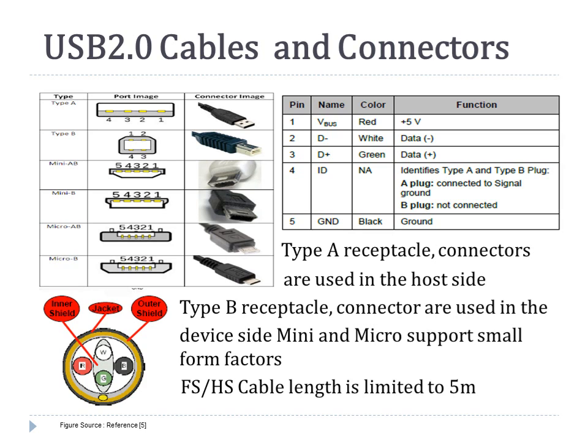It uses 2 lines for differential data signaling, which is D plus and D minus. It also has a power line in the bus, and this is a unique feature of USB, where we can deliver power to the peripherals also using the same bus. It has an ID pin which demarcates the host and the device, and is mostly used in the USB OTG specification, where the role of the host and device can be dynamically determined, and it also has a ground line.